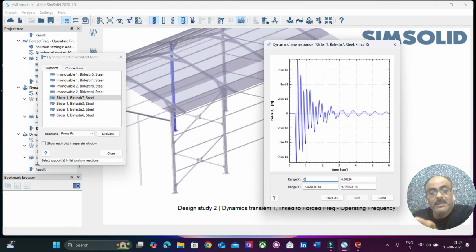So there will be the influence of the loading that is going to act from the bottom, the base excitation, whereas the impact of that base excitation on the other immovable structures is going to be lesser. So the end members are all immovable, fixed, and the inner members are made to be on the spring support or on some sort of soil foundation.